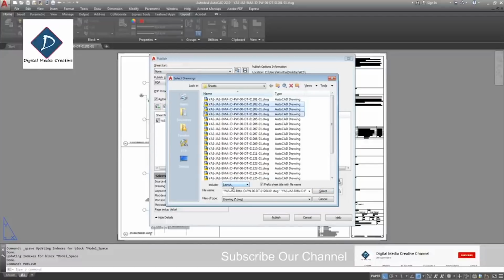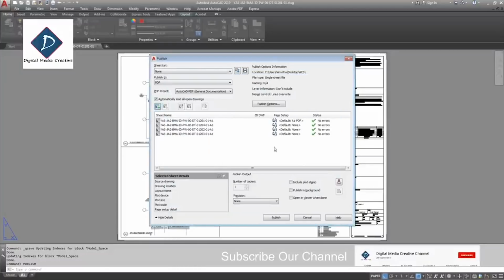Make sure only layouts, you don't want to include model space. Okay, so I added already. Then what you need to do, you can see the page setup only applied to the first one. Okay, so we need to apply to the other sheets also.